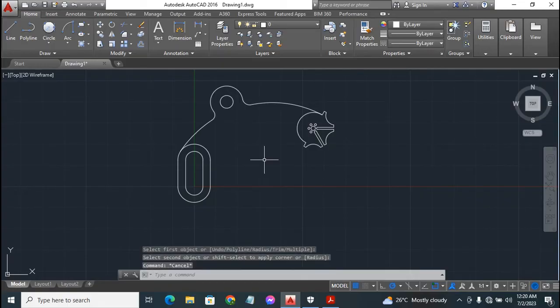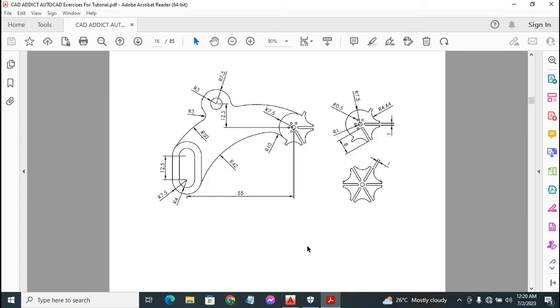So next up, we'll go back to our PDF document. Looking at this, you see that we'll have another curve here of radius 42 millimeters, while we'll have a curve here as well of radius 10 millimeters. In order to draw in that curve, first off, as you can see, this curve here is not touching this directly. It's lying off from this other curve.